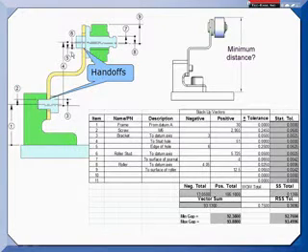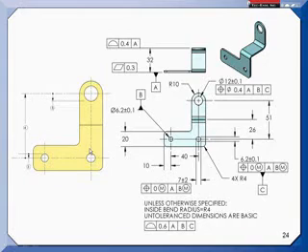So when I do my complete tolerance analysis and we look over here at the results, the worst on worst, or WOW tolerance, ends up being 0.75 millimeters when you add up all your tolerances that go into this assembly. Now, if I do what the shop wanted, oh, I'm sorry, here's another view of the vectors. I'll show you this first. So we handed off here to this hole, so I went down to the datum plane, then up to the center of that hole, and then down to this edge of the larger hole.